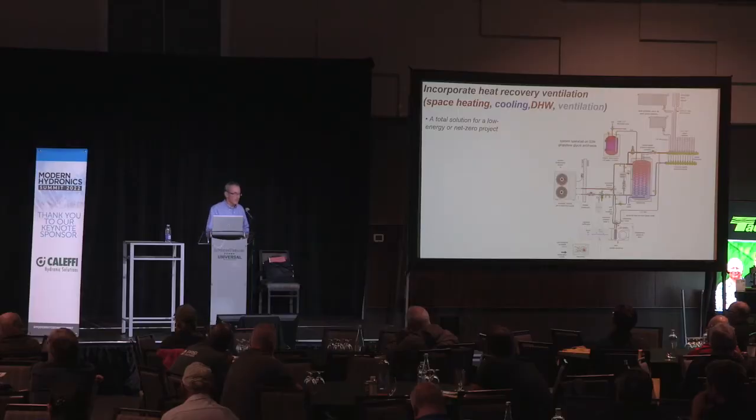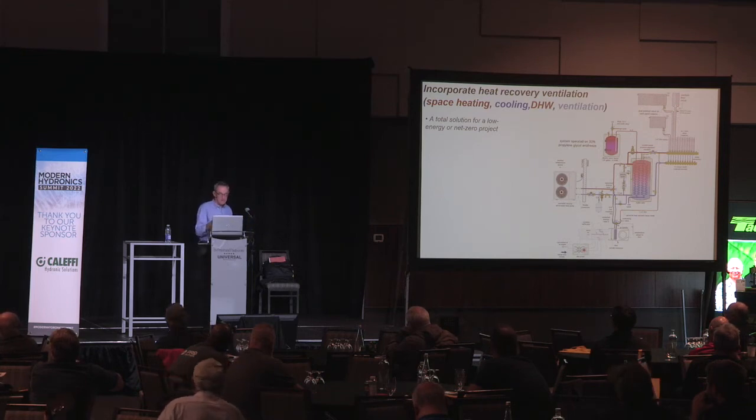Well, you've got a tank full of warm water. You've got a circulator up there that is running basically 24/7 on a home run system. These pressure-regulated variable speed circulators, you can run them 24 hours a day in the wintertime. If all the radiator valves are closed, they drop down to around 9 or 10 watts, almost a trivial amount of power. When a radiator valve opens, they reawaken, they come out of sleep mode and basically speed up as necessary. So the circulator's running, waiting for TRVs to open up.